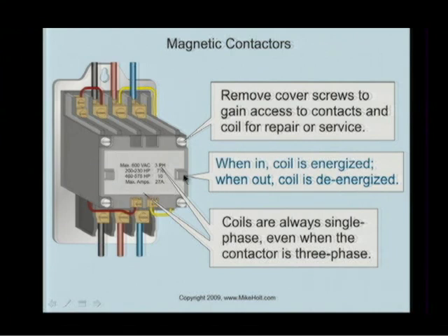If you want to, turn it off, lock it out, de-energize it, tag it, and then it's troubleshooting to find out if you have continuity there, or maybe use an ohm meter to find out what the contact resistance is. Any other comments you guys want to make at all? All right. But for a fact, that can be pushed, and it's something that we don't want to do.